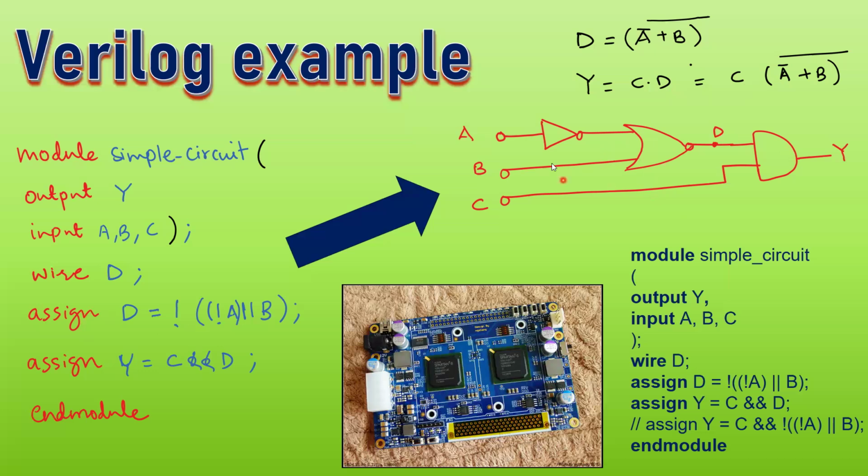When you make a coding and then you simulate, then you send the code to the synthesis tool that creates your gate level netlist. So basically synthesis tools understand by this expression what you want to implement. Accordingly, it assigns some logic gates to your circuit as per the description. So the special keyword I will use here is assign.